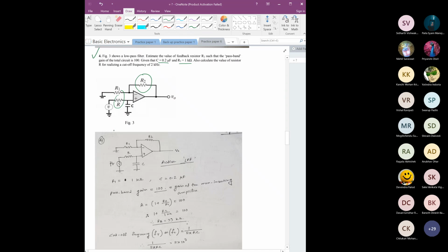So here you can see the signal source, this V1, and it has been applied to an RC circuit, and this RC circuit is fed to this op amp. So you can consider the remaining part to be an amplifier. The signal has been fed to an RC circuit; this is R, this is C, and you know this configuration is nothing but a low pass filter configuration. And what is the output here? That has again been fed to an amplifier.